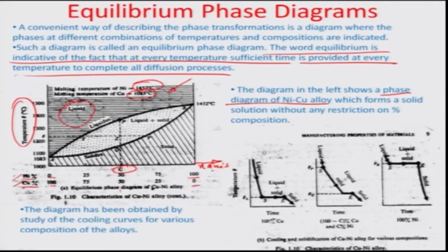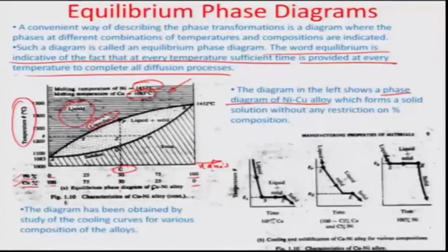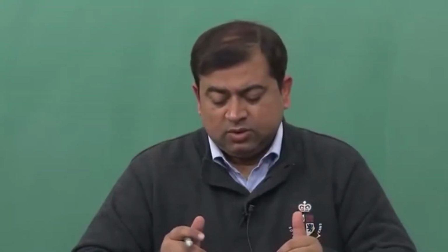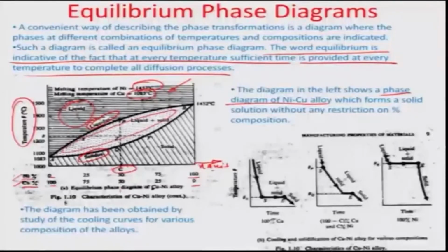You have something called the liquidus line, which illustrates the point beyond which solidification will start to happen, although not complete, and a solidus line, which gives you an idea of when the solidification process is complete. You can see this dotted phase in between, which is related to a mixture of solid and liquid.